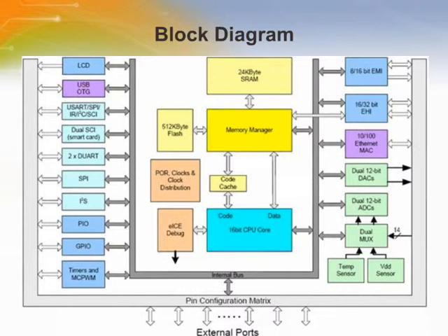The eCOG1X has a rich set of serial peripherals including UARTs, I2C, SPI, Smart Card, and Infra-Red protocol engines. A full set of hardware timer functions is available in the eCOG1X, providing 8 independent timers capable of performing functions such as clock generation, PWM generation, and infrared signal modulation.